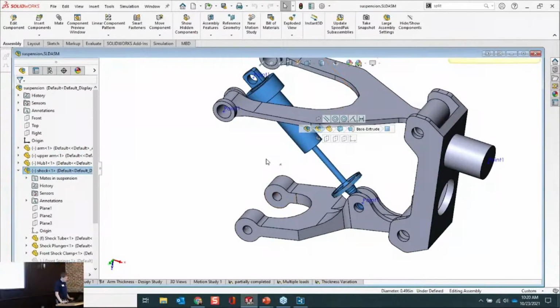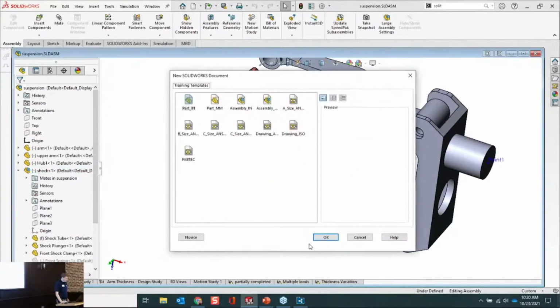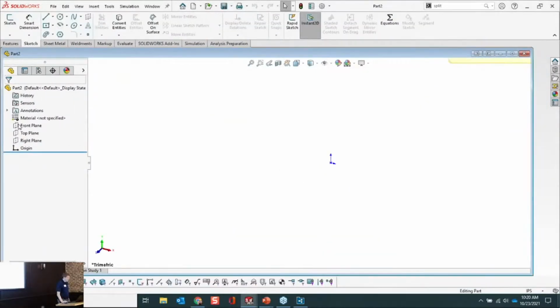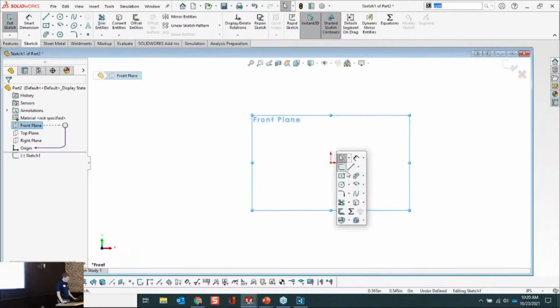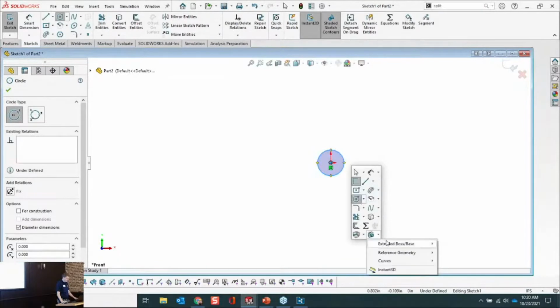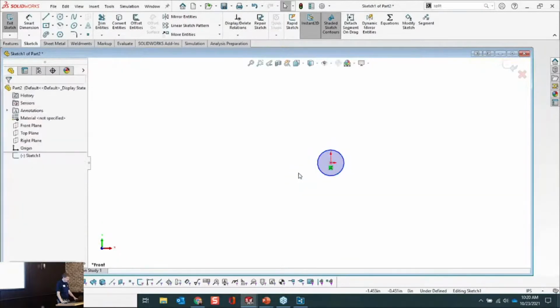Now, if you're in a sketch, it works similarly, just that it is there to speed you up. So everybody knows about the confirmation corner in the top right corner. So if I create a sketch and I want to confirm that sketch, I can hit the D key and it snaps the confirmation corner from there to the mouse. So the S and the D key are right next to each other on the keyboard for that reason. They are in conjunction the two buttons that make you go the fastest when combined together. And that's why that one made my list.